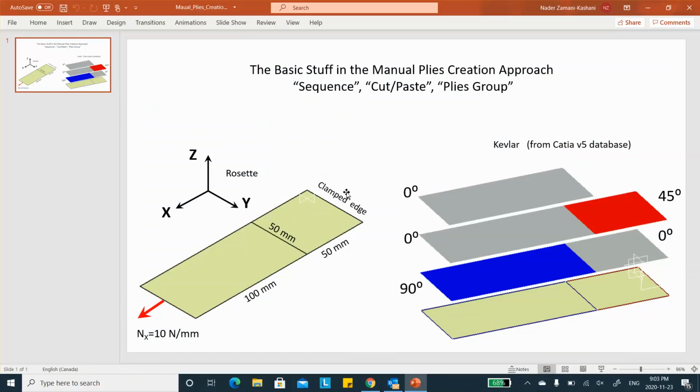The idea was I created some plies manually, but later on, or even at the time that I created them, I could have created one and then copy and paste, okay? And then I had to go and change each one of those. I had to change the particular orientation or a particular material if it was changing. This is not practical when you have a lot of plies, so maybe there may be an easier way of doing it, and this is what we're going to do next.